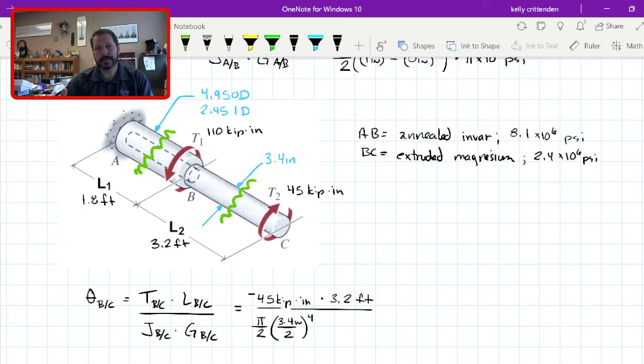It's often easier to use the diameter, maybe not mathematically, but in real life, because if I go to measure the diameter of this pin, I pick up some calipers, and when I measure it, I measure the outside diameter. You don't have a tool that just measures the radius.